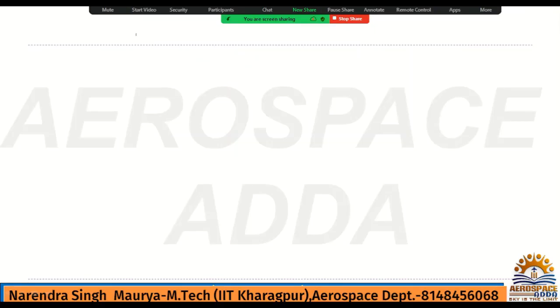So what is burning rate? It is a very special parameter, burning rate. Basically, the burning rate is defined as the recession of the propellant surface in a direction perpendicular to the burning surface per unit time.